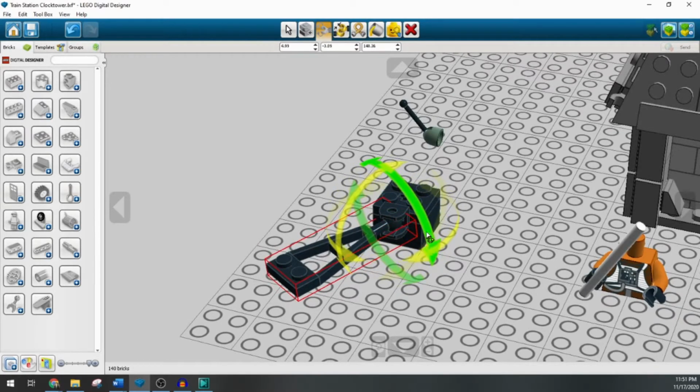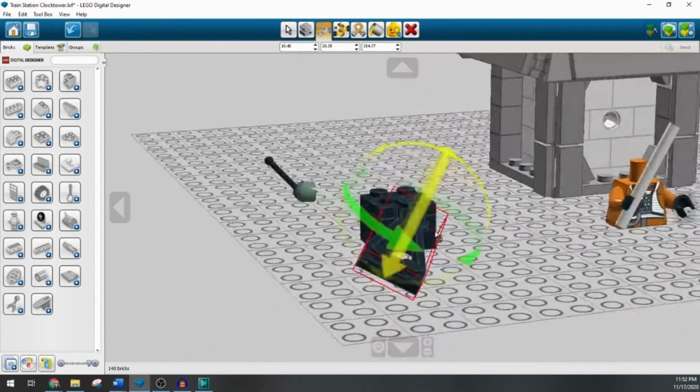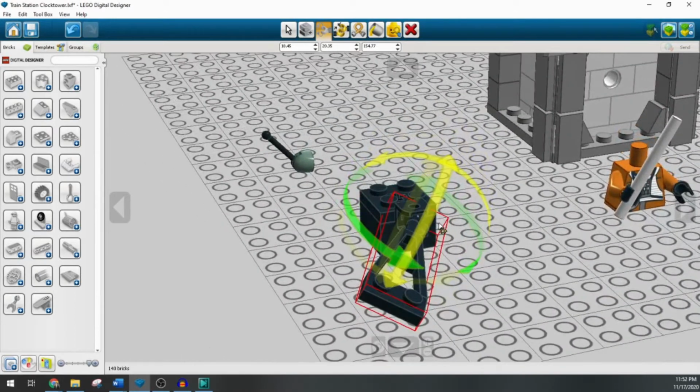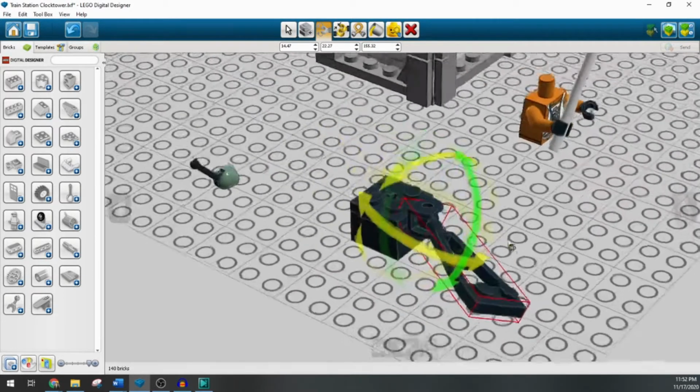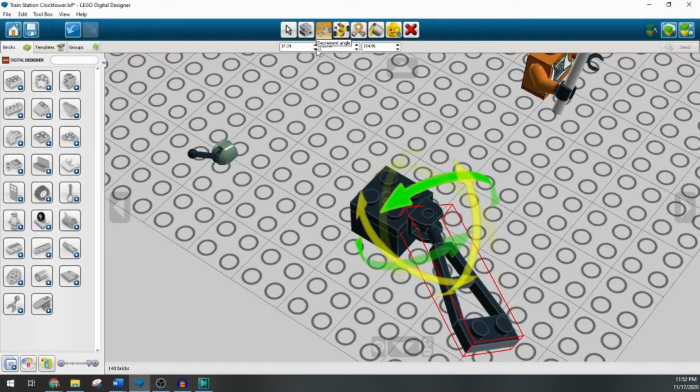So the toe balls are really nice because you can get those 3 degrees of rotation going. Just kind of be careful about your orientation. The best thing you can do is find a spot where you're grabbing the right axis to turn. And in this case, it's helpful to know which one you're actually applying here because it turns green. You also have 3 entries up at the top, so that you can individually control each axis of rotation.